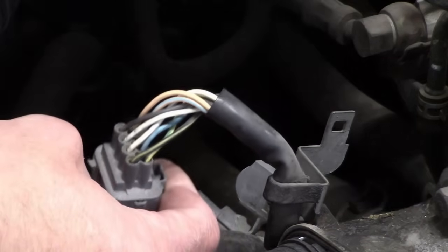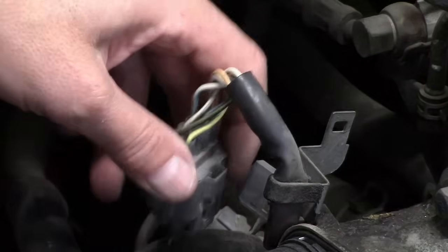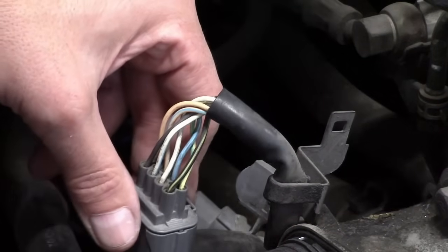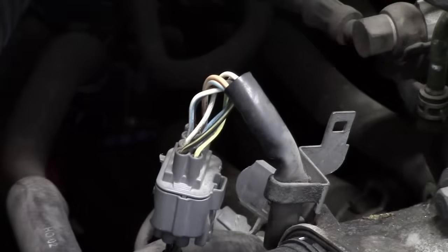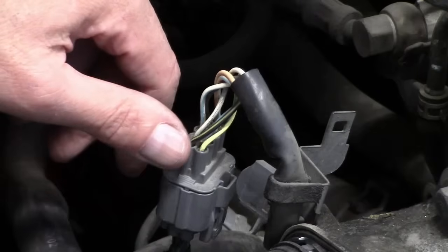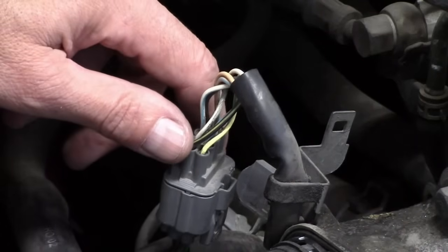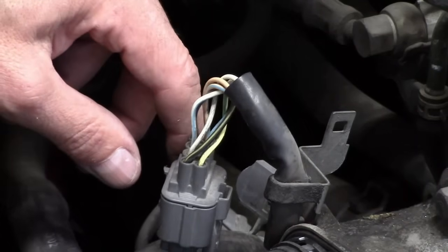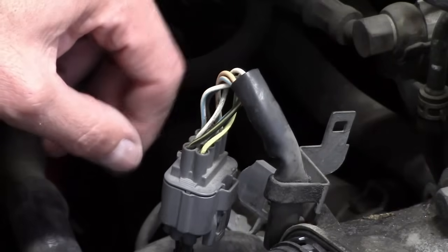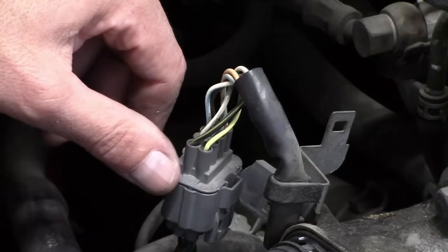I'm not sure. I could tell from the wiring, but I don't see why there would be 8 wires leading into this distributor. My guess, of course, is you've got a single coil in there, like with any distributor model. So you're going to have a coil signal input, a reference, and a ground. There's 3 wires. You would have up to 3 on your crank sensor. That's 6. I don't know where the other 2 could possibly come from.